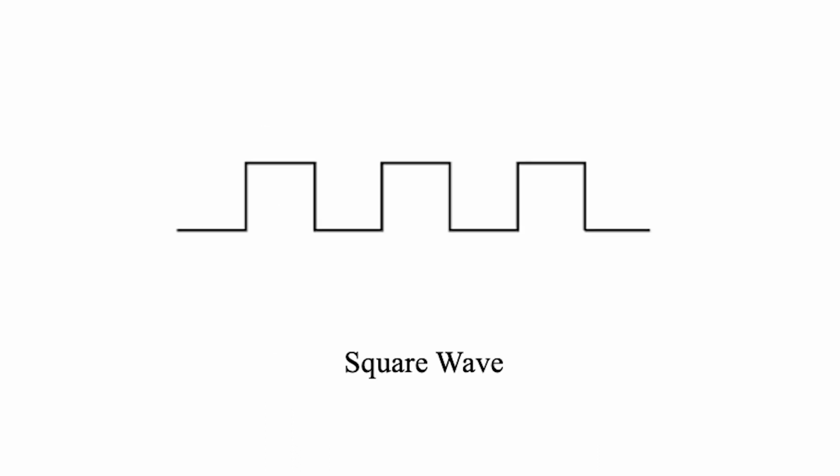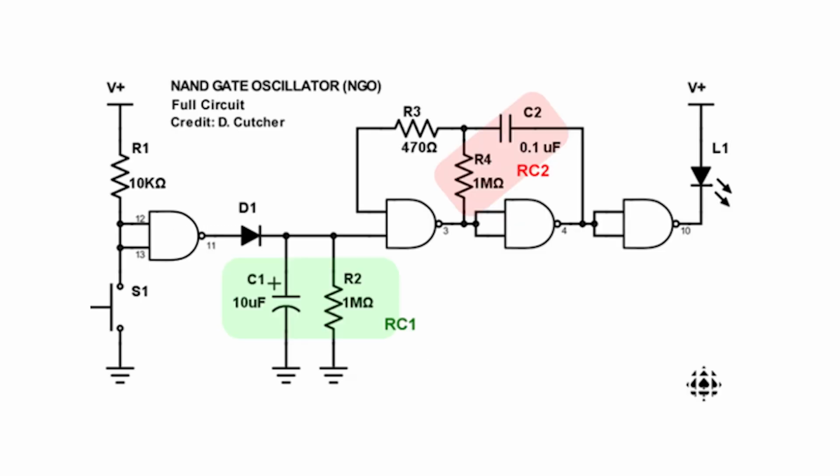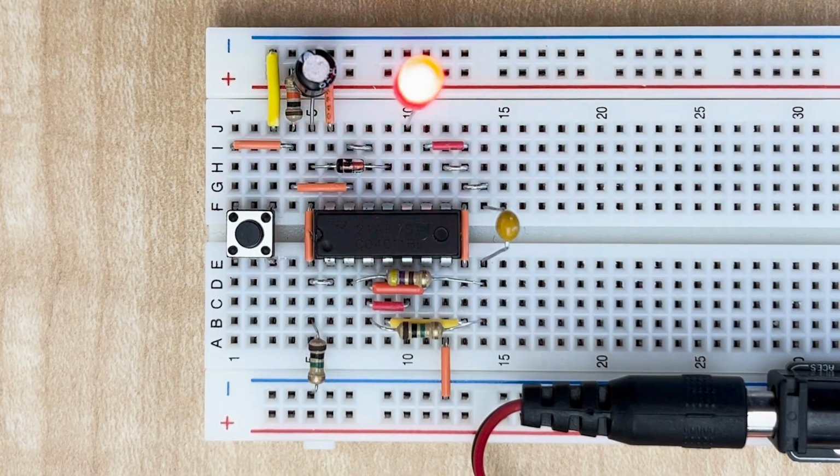This clock signal is a periodic waveform with a specific frequency which is used to synchronize the operation of the circuits. It provides a timing reference for a lot of operations within a digital system, ensuring that different parts of the system operate together. In the context of the counting circuit, the signal generated by the NAND gate oscillator using the 4011 chip determines the speed at which the counting circuit increments or decrements, depending on if the circuit is counting up or down.